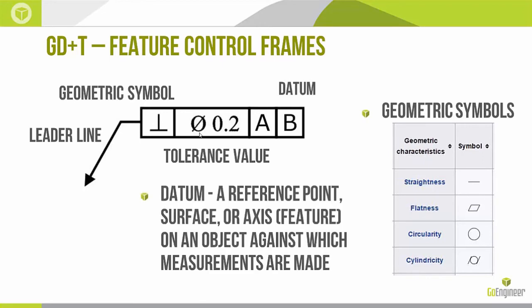And once again, a datum can be a lot of different things. It can be a reference point, surface, or axis. And I kind of just generalize that into features, right? We're just talking about different locations on the part that we can grab, fixture to, zero on, right? Just kind of finding an anchor point or a 0 point from which to base other features.